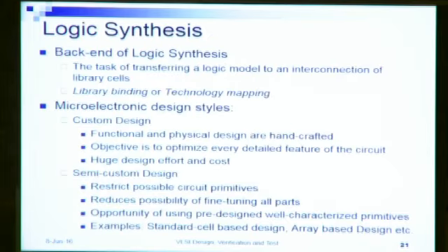Now we come to the back end of the logic synthesis step. The back end of the logic synthesis step does this. It does the task of transforming the logic model to an interconnection of library cells. This is popularly known as library binding or technology mapping. So it will take you from the gate level design to the transistor level design.